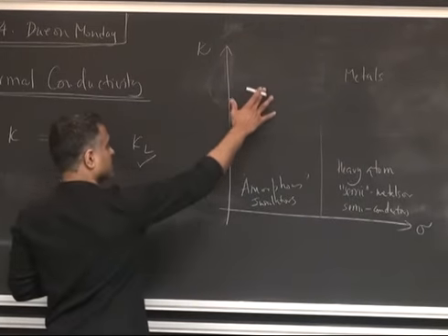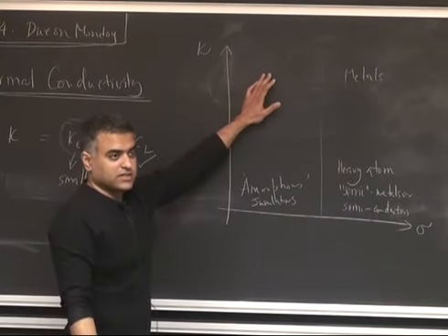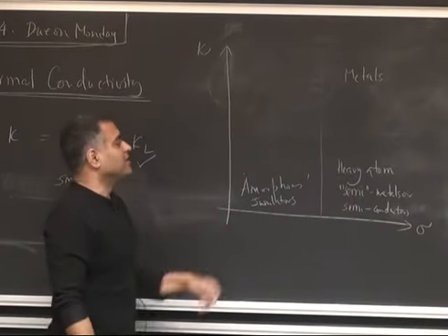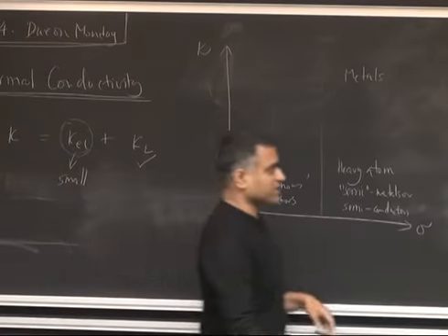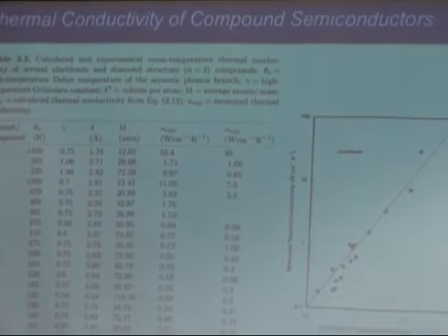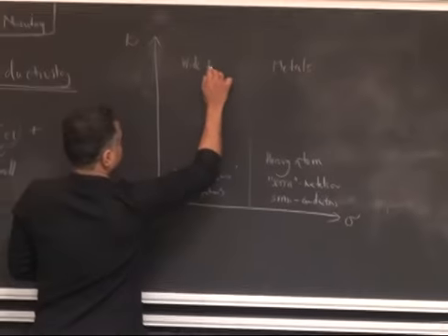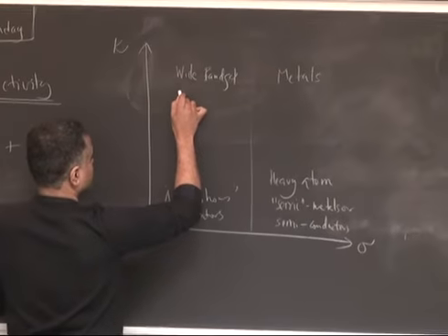And what about this end, the top left? So very low electrical conductivity, very high thermal conductivity. This is even more non-intuitive sometimes. Right? But what are the materials there? Examples. Crystalline with a high band gap, right? An example being diamond is the best example. It sits on the top of the periodic table, in group 4. So these are, you can say, very wide band gap crystalline insulators, but also light atoms and all that, right?